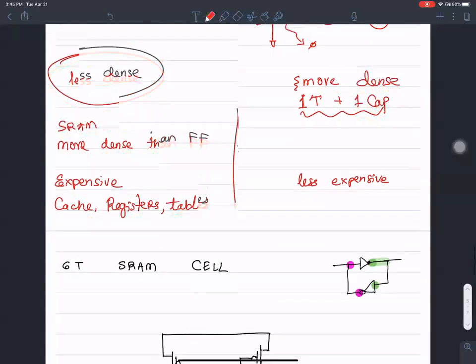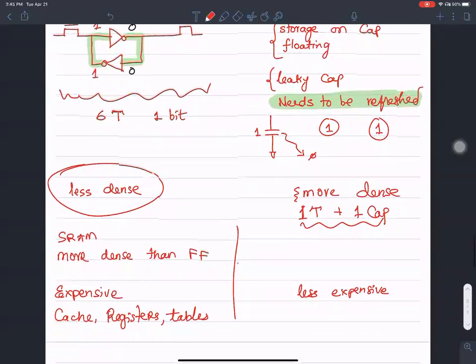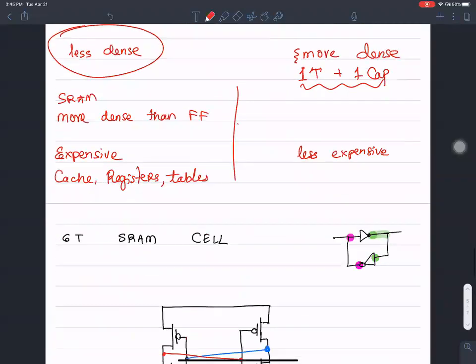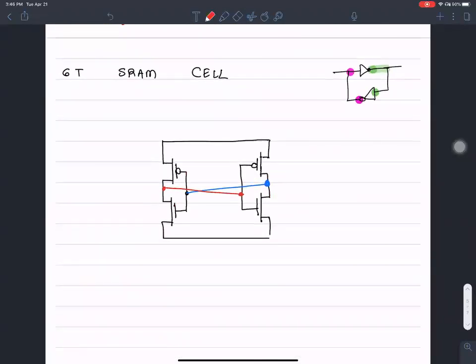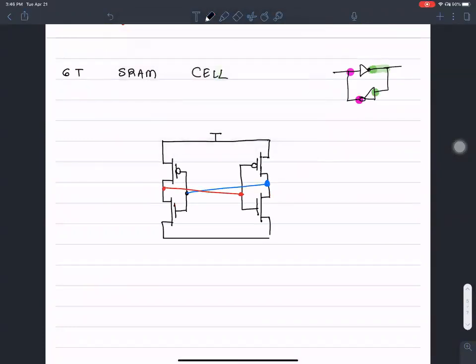The idea is that the support circuitry that is necessary to keep refreshing the DRAM slows it down. The capacitance slows it down further. And then the operating current on these transistors is high enough that it keeps them fast. So because of the involved capacitance and the support circuitry, the DRAM is slower than SRAM.